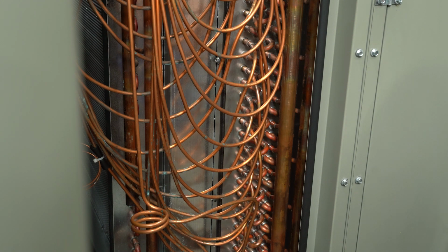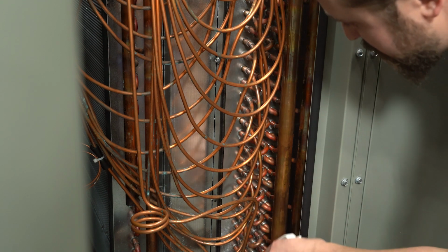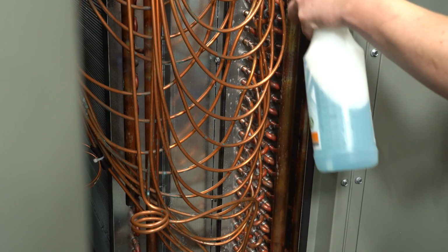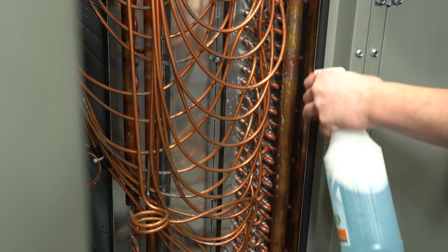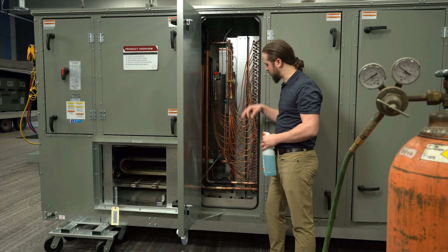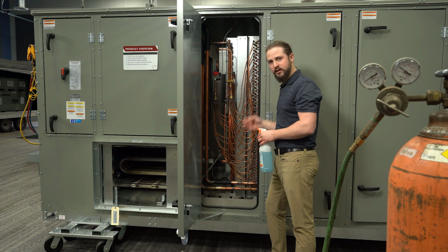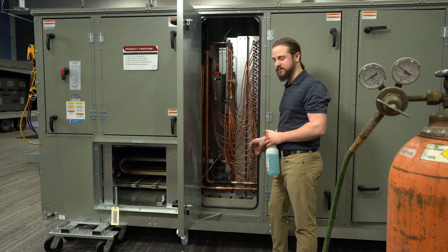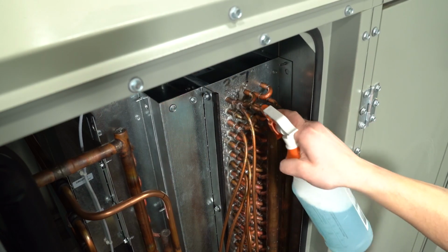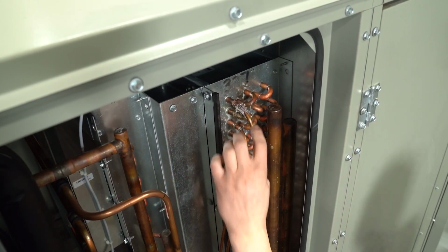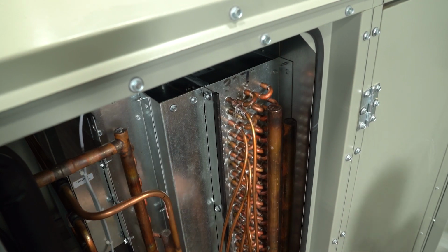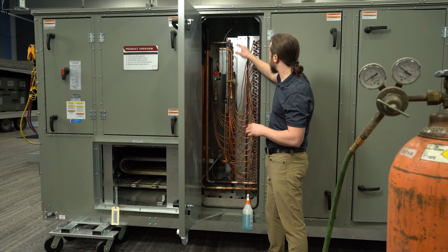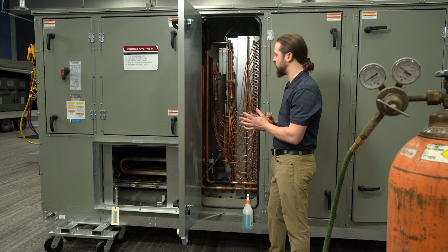Okay, now let's spray down our coil section here. Let's pretty much just spray everything down, all the U-bends, any soap that sprays out rapidly or just starts to create fine foam. In some cases, it actually is helpful to hold a flashlight looking straight up and down. You'll actually be able to see soap spraying out at you that wouldn't have created bubbles. Okay, we're spraying down distributors. Oh, here we go. We have a leak on, if we trace this out, looks like the circuit B distributor line. Next, let's get this leak fixed up, and then we'll transition on to vac and charge.